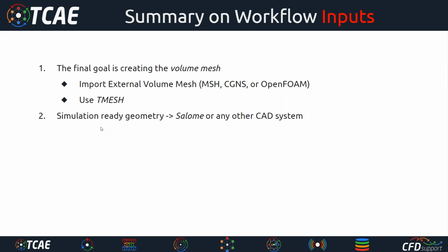What you are going to do is split your model into several components, for good reasons, because some components are rotating, right? So we need to split them to allow them to rotate, and some components are static. But the basic principle is you are going to split your model into components. In our case today, it's the centrifugal fan. So component number one can be the inlet tube, the suction tube, basically. Then it can be the impeller, for example, which is rotating.